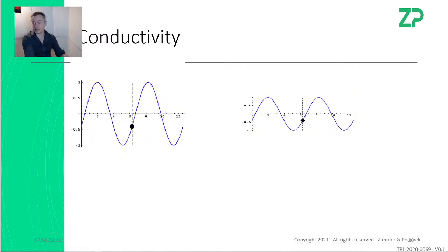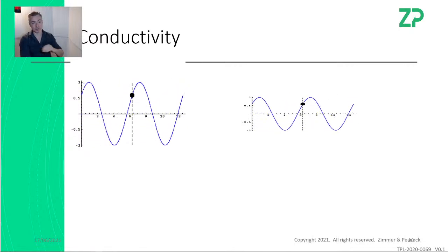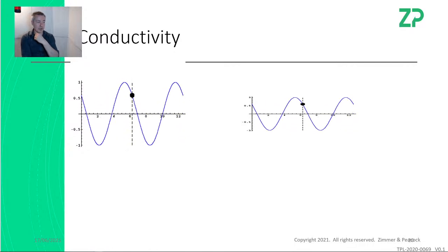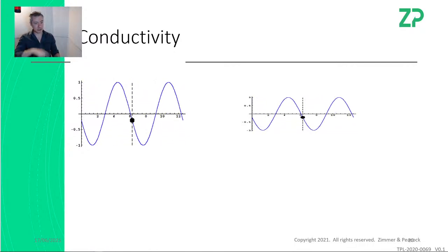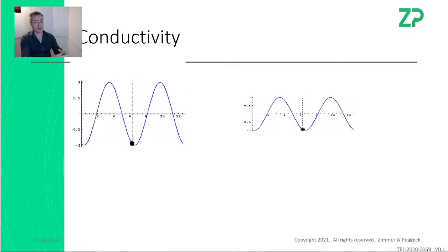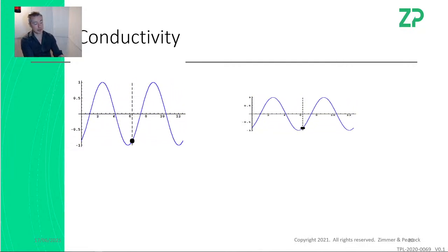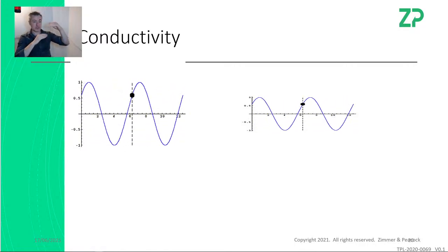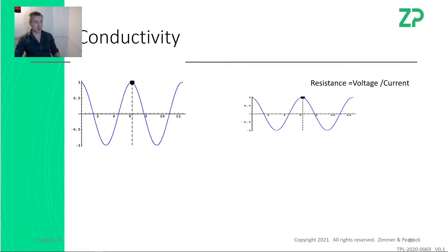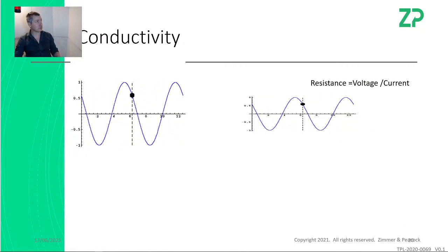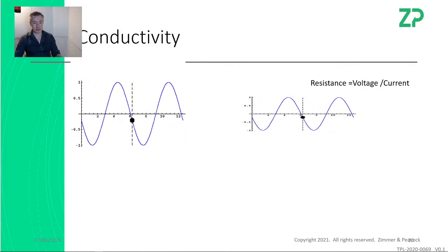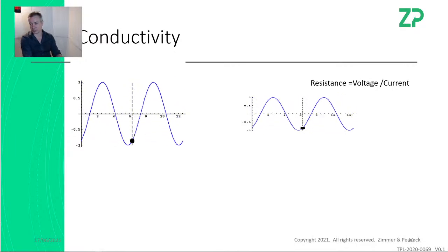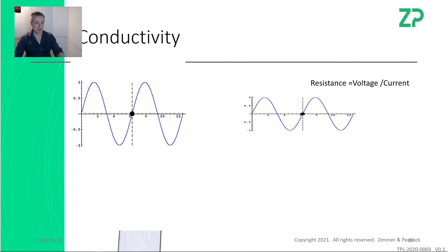So I started having a look, but I haven't found an answer yet whether you can do this through Arduino. I imagine you probably can, but essentially the Arduino has to give out a sinusoidal wave with a frequency of about 10,000 hertz and about plus or minus 10 millivolt amplitude, and then you have to look at the current, and the ratio between the voltage and current is the resistance. So I haven't so much answered your question about Arduino. I've got a suspicion it could happen. I just haven't found out how to do it.